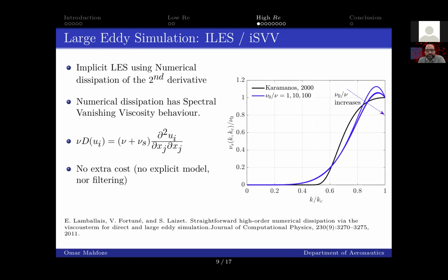But we did some study using a channel flow where the first point in the grid is over y plus equal 5, and we managed to capture most of the velocity profiles and the kinetic energy. But for this one, yeah, I tried to make it as close as possible to the DNS, especially near the wall. Okay. Thank you.